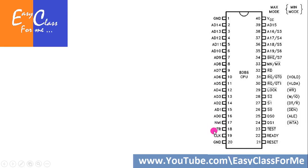However, in this INTR pin, whatever interrupt you give, depending upon the choice of the processor, whether it is performing a critical operation or not, it will deny or accept your request. So there is a difference between these two pins. Non-maskable interrupts cannot be neglected by the processor and they have to be served by it, but the INTR pin, depending upon the status of what the processor is doing, can deny or accept your request.